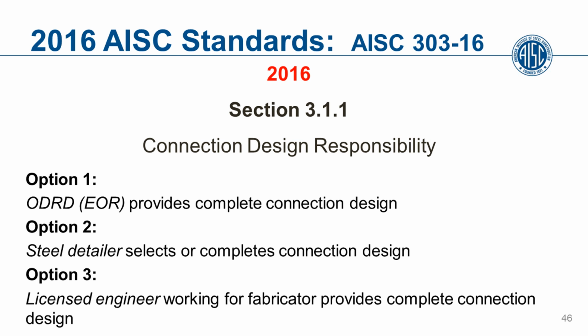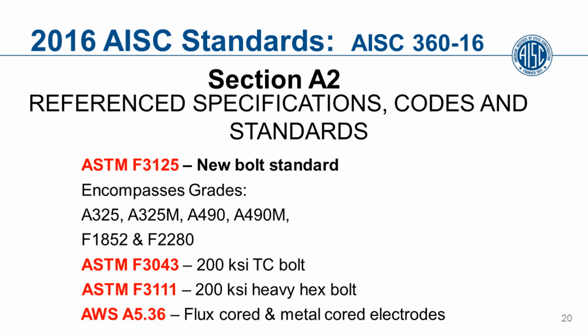Okay, thank you, Larry. Our next question, you referred to some new 200 KSI bolts. Can these bolts be hot dip galvanized? No. The short answer is no. The 200 KSI bolts cannot be hot dip galvanized.